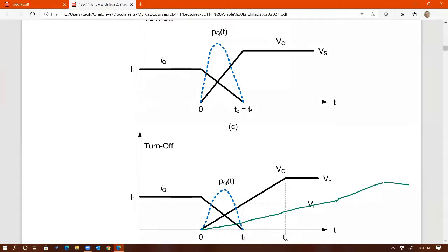That will interfere with the frequency of switching. Very good, very good. There's always a trade-off, right? Something has to give. By increasing the capacitance, you are basically increasing the switching transition time. You are taking away some time from the duty cycle. So now your duty cycle is going to be more limited by increasing the capacitance.